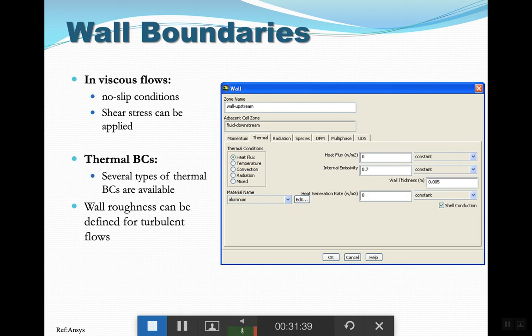So you're not saying the velocity on the wall is 0, and you're not saying it goes with free velocity, but you're saying that for whatever reason, mostly coating in the physical world, the velocity slows down, but it doesn't get to 0. So these are the three viscous conditions that you provide on the wall.